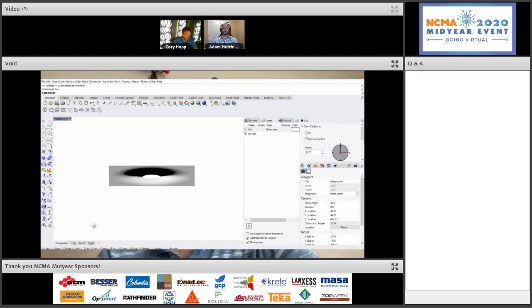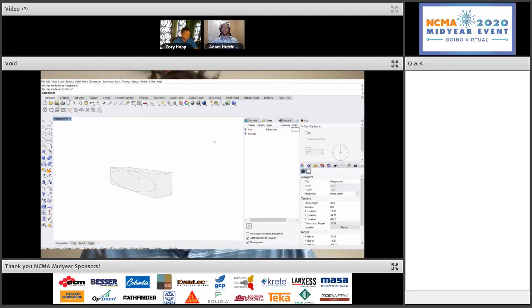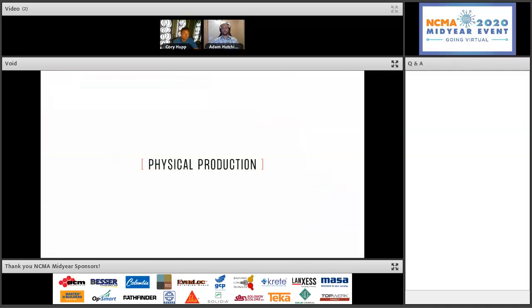And with this simple and elegant form, the brick really only needed basic Rhino tool sets. We didn't need any external plugins like Grasshopper. The main torus shape on the front essentially used 4 curves on each side, and then we just lofted to make this little funnel type shape. And then the rest of the brick was just a box encasing that shape. The simplicity of this unit design made the modeling process super quick, and it gave us a lot of time to start working on the CNC machine and physically making this brick.